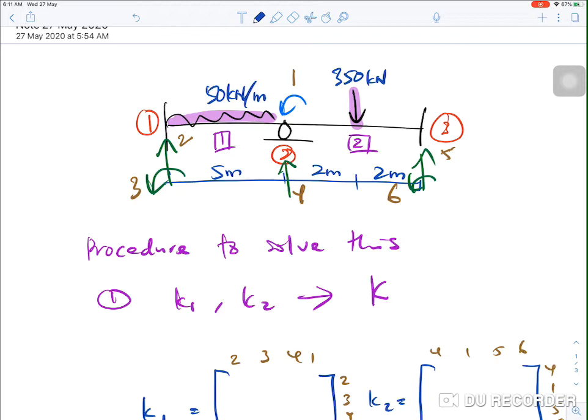So if this is the question, this beam consists of three nodes, and there is one unknown rotation, or one degree of freedom in the unconstrained system. For the remaining, the reactions at the support, there are 5 unknown reactions, not considering the axial force in the system.